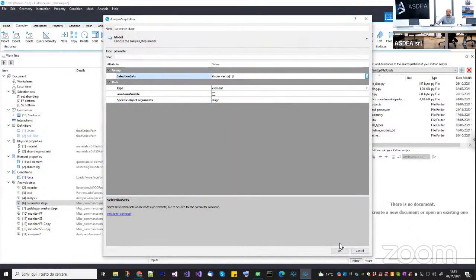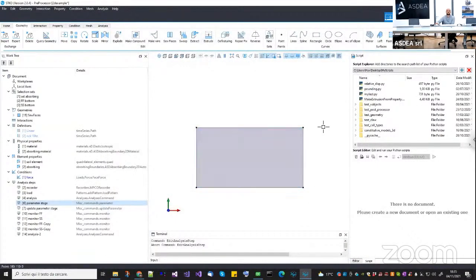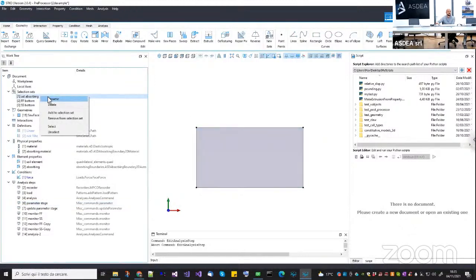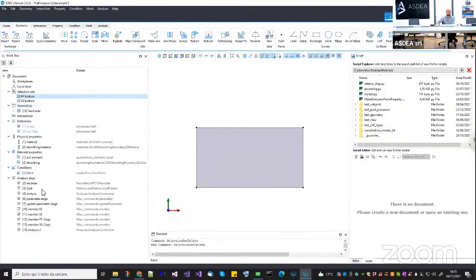Now, this is not possible, of course, because the element has not been created here at this point. The element will be generated automatically by STKO. So how do you update a parameter for an element that is not in STKO? Actually, it's much easier. You don't even need this one. Delete. You don't need the parameter and update parameter.